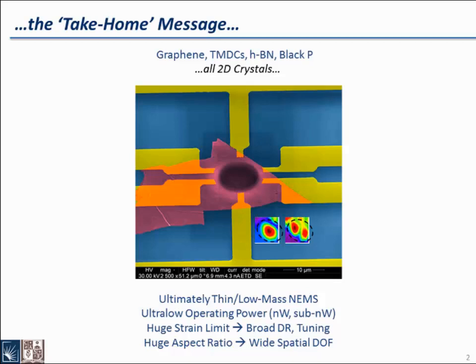In the past few years, we have made a lot of effort trying to develop this nanoscale electromechanical or electro-optomechanical device platform. As you can see, showing this color-enhanced scanning electron micrograph, we have this blue-colored silicon oxide region, and we have patterned six electrodes by conventional photo and electron beam lithography.